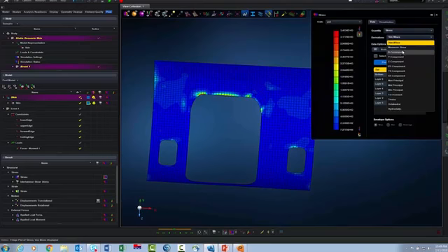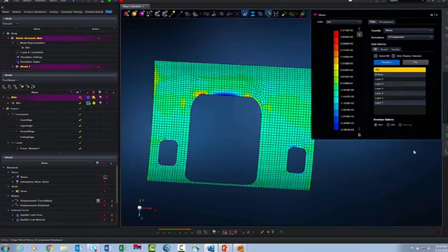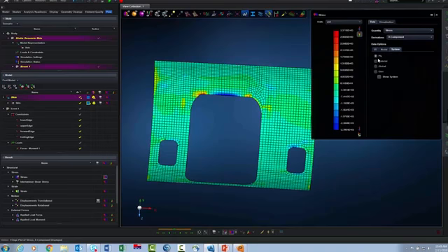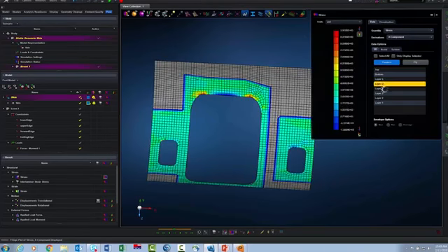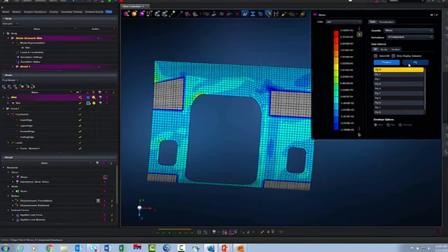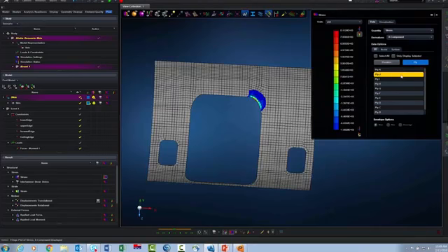Okay, and let's look at sigma x. Okay, and I know that I'm looking at sigma x because I can go to the system and I see that I'm looking at the ply material orientation versus material, which would be the material axes for the panel itself. Okay, I can look at results for the individual zone layers, or I can also look at the results for the individual sheets or the individual plies.